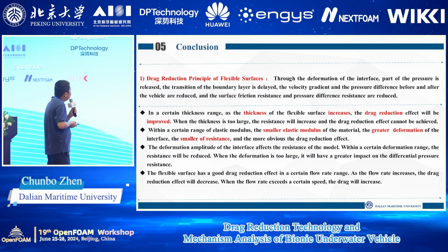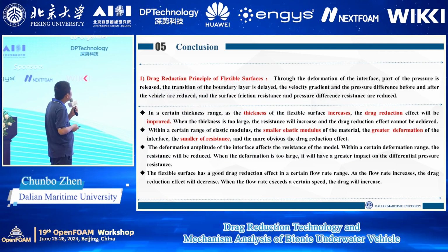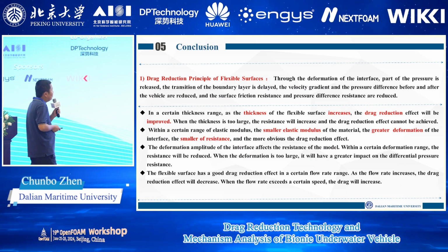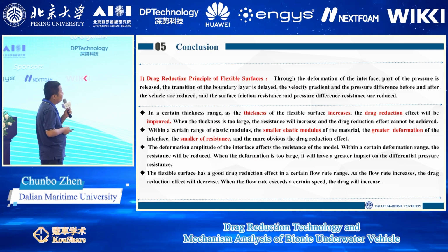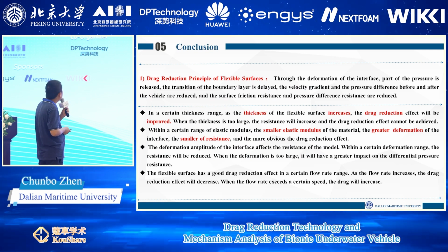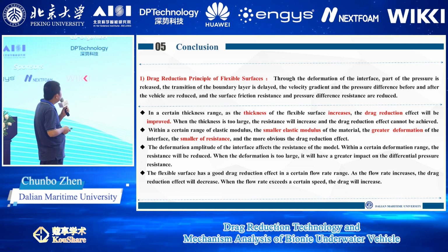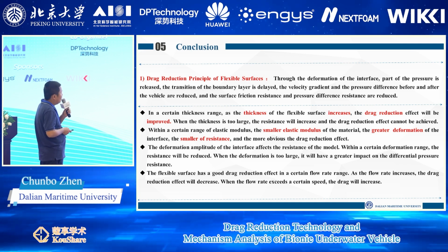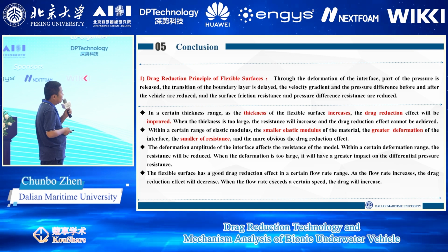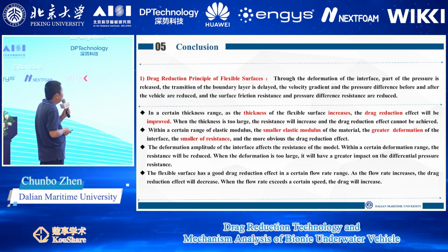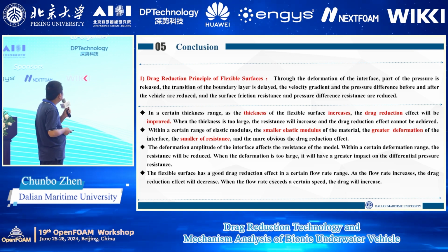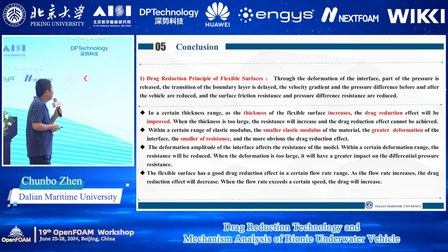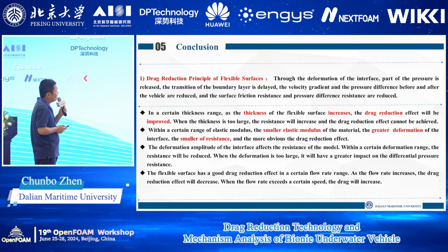The first one is about the drag reduction principle of flexible surface. Through the deformation of interface, part of the pressure is released. The transition of the boundary layer is delayed. The velocity gradient and the pressure difference before and after the vehicle are reduced, and the surface friction resistance and pressure difference resistance are reduced.